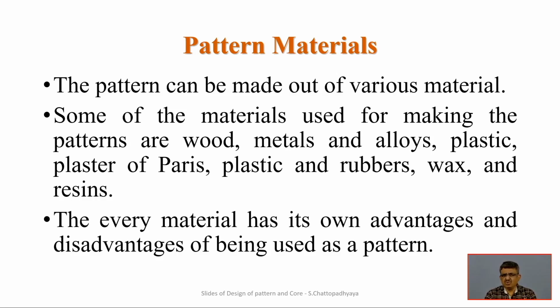Wax is used in investment casting as a sacrificial pattern, and now with the advent of 3D printing technology, rapid prototyping technology, the advantage is that wax patterns can be 3D printed, and 3D printing has a tremendous advantage that it is not very operator specific. Once we have a good CAD model, we can print the pattern with its initial dimensional inaccuracies and surface finish. But the hassle of manufacturing those patterns is minimal if we are using 3D printing technology, and wax patterns can be produced by 3D printing, and resins also in a few cases.